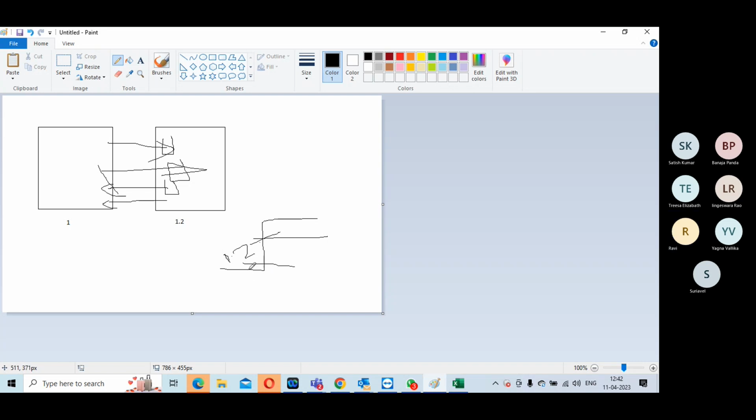So if it is like 0.9 to 1, you may not require it for the output pins from here. Inputs are required in this case because this is a higher voltage domain, and this block won't understand 1 volt, since the signal will anyway only hit 1 volt. So you add a clamp cell. Whether it is required or not is based on the voltage difference between these two. If that is 2 volts, then you need to add one. Otherwise, you can add a clamp cell to keep it at the level of 1 volt. The clamp will clamp it at 1 volt.